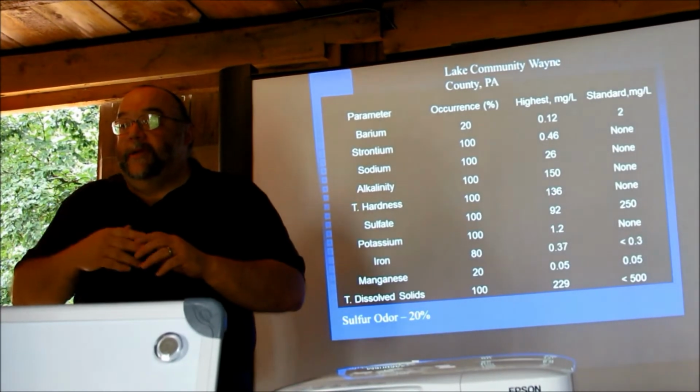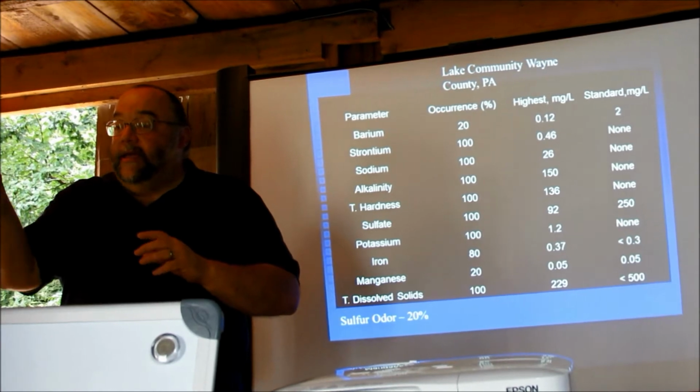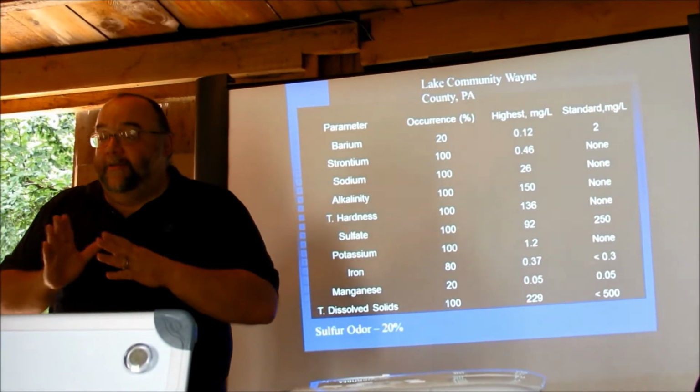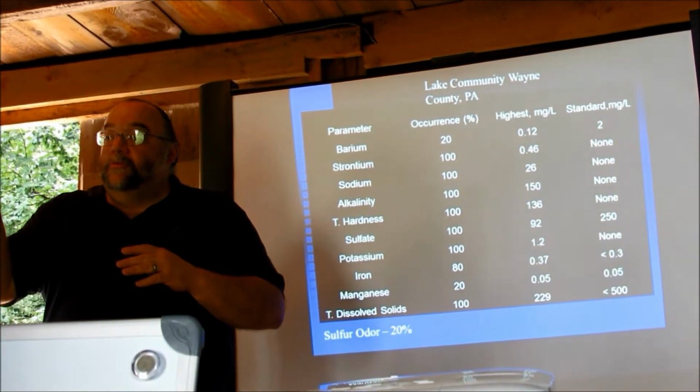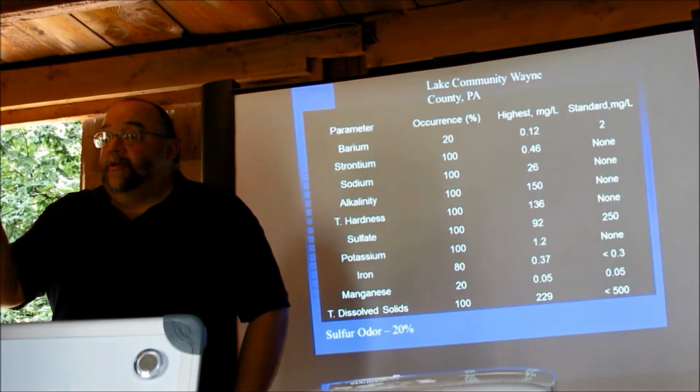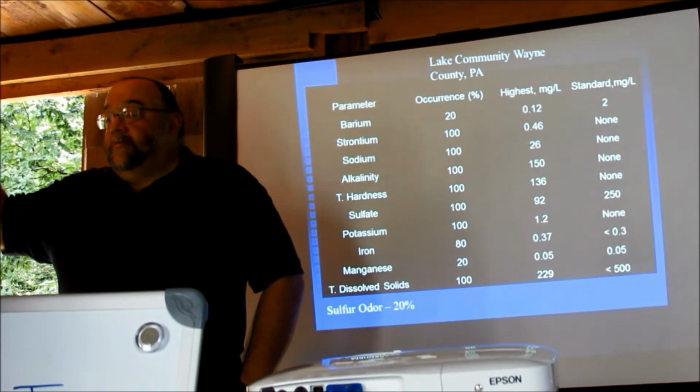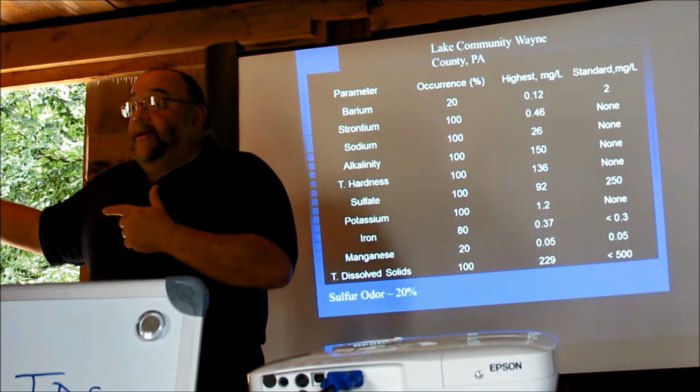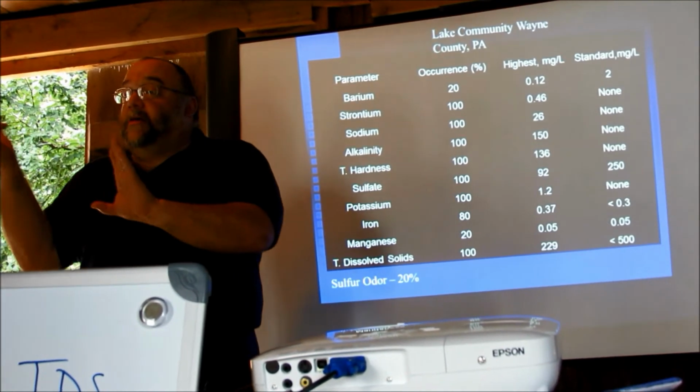What you can do with those meters, if that's the meter you have, is do what you can with it. You can go measure the TDS, and then take a sample to the lab and determine the correction factor.